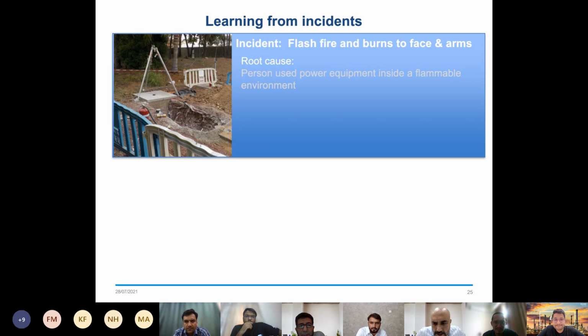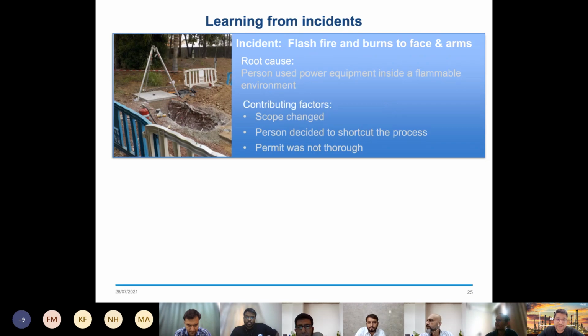Probably using non-flammable equipment. Yeah, we must use equipment that is ATEX rated or certified with CE marking. These are all explosion-proof types, or with the EX marking. So you have to remember either ATEX certification or the EX marking. These are all flameproof if you're going to use them at the retail site, at the hazardous zone. So be cautious of that equipment as well, because it's quite important.